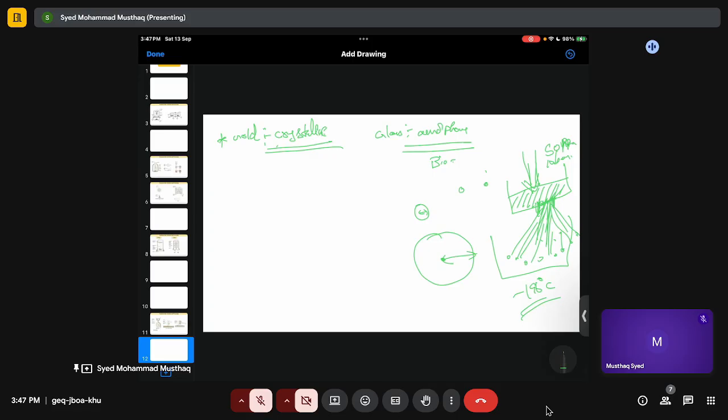These two terms are defined along with convection. So you have conductivity, dimension, and convection. Heat has three ways of transfer: conduction, convection, radiation. Conduction is mainly through phonons, the collective oscillation of atoms. Please don't confuse it with plasmons. Plasmon is collective oscillation of electrons. Phonons are collective oscillation of atoms.